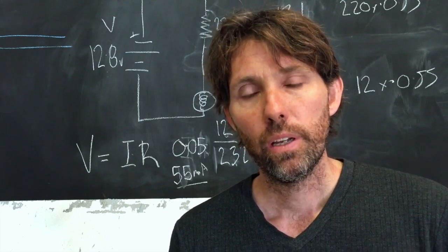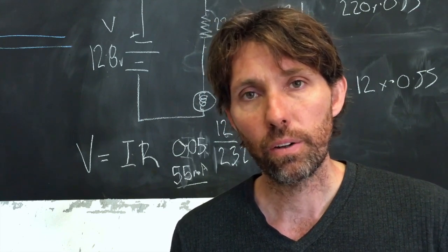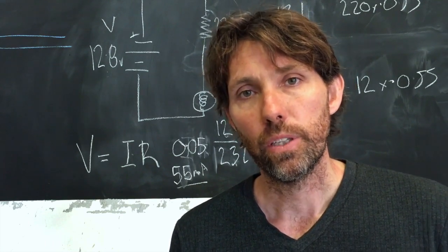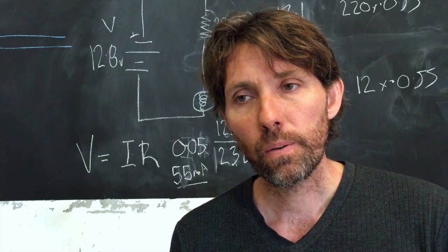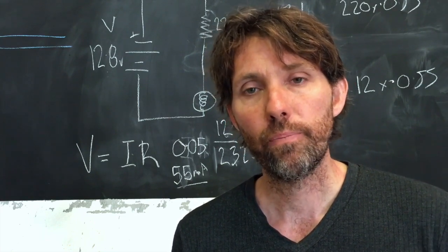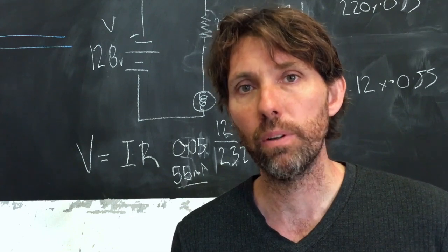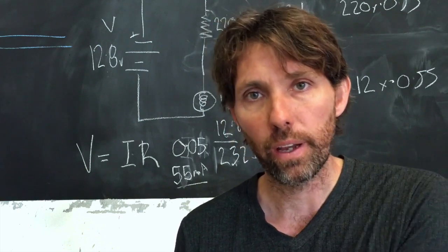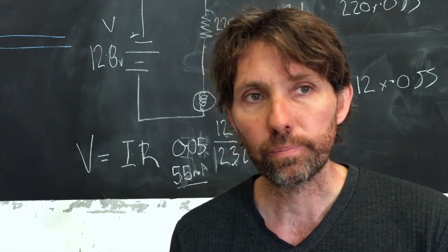If you measure in series the current flow, you'll see the current's really low in some circumstances because there's high resistance in the line. Okay, so getting 12 volts doesn't mean you're getting a lot of current, and it doesn't mean that by the time you get to that point in the wire, most of that 12 volts hasn't dropped over other sections of high resistance.